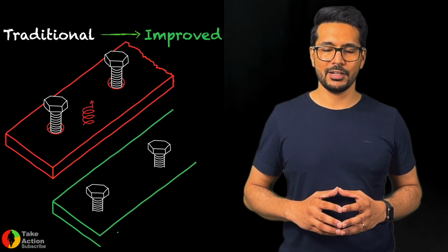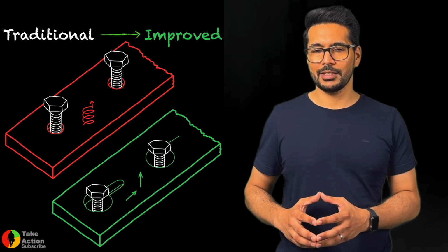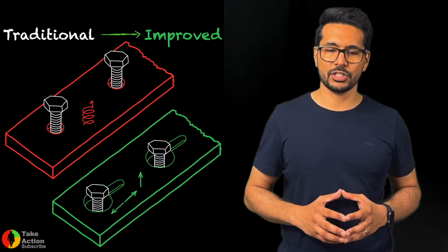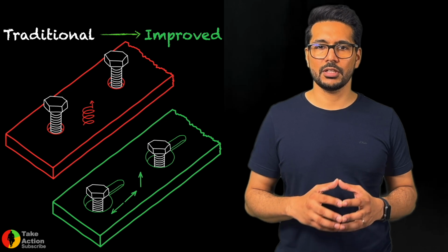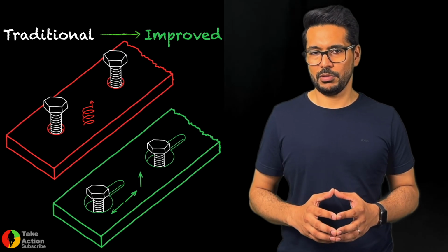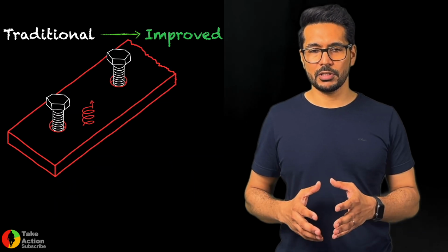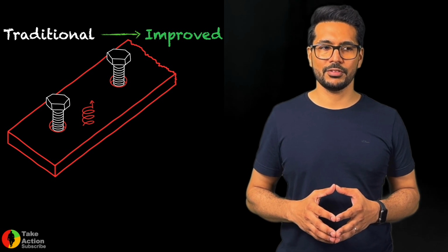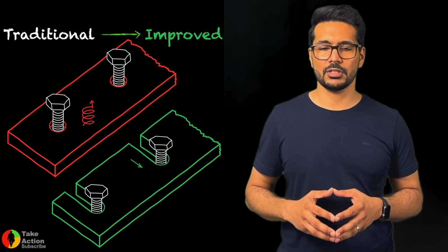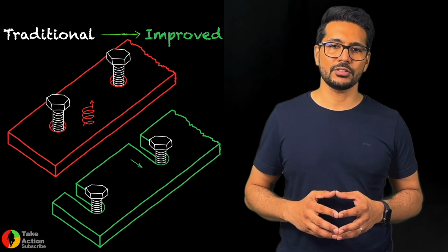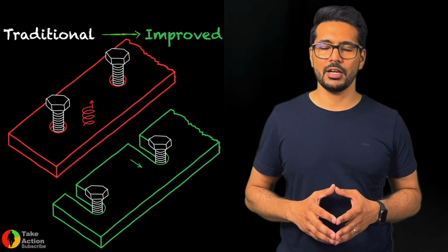After turning one time, the plate will be loose, and then you can slide it in one direction and you can easily remove a plate or any part. So it's one thread loosening system here. Or there is another idea in similar cases that you can have C-slots instead of traditional holes, in which you just unscrew one thread of the screw, and after that you can just slide and remove the part.